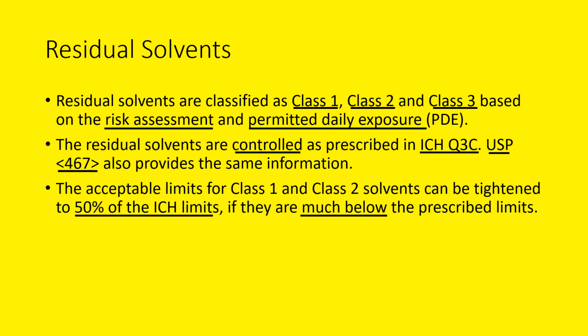Even if you get very small amounts of residual solvents routinely, it is acceptable to limit the specifications to about 50%. For example, if methanol is present in the range of 100 to 200 ppm on a routine screening against the actual limit of not more than 3000 ppm, it is adequate to revise the specification to not more than 1500 ppm.